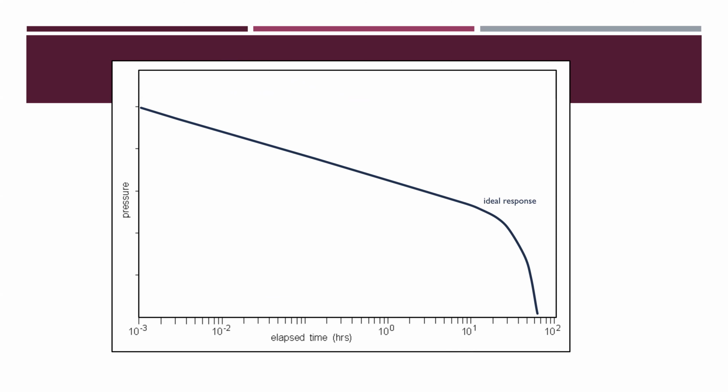However, in reality, either wellbore storage or skin, or both of them, will be there. If we have only wellbore storage without skin, it will overlap the ideal scenario. Just the beginning of the test will be masked. The real pressure response will be masked by what we call a storage effect. However, the rest is still overlapping.